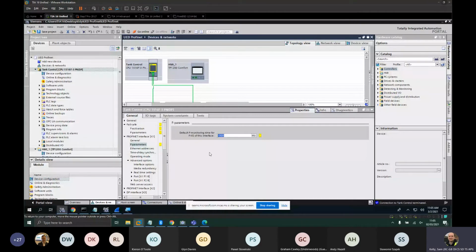So it's something that you need to take into consideration when you're evaluating your fail-safe projects. That is, is my response time going to be fast enough for the application? If not, you may have to do other preventative measures. For example, increase the distance between a gate or a light curtain and the process which could cause harm. So these are things that you need to take into account when you do your auditing or health and safety analysis. Risk assessment, that's what I was looking for. Okay. So that kind of answers your question a little bit? Hopefully.